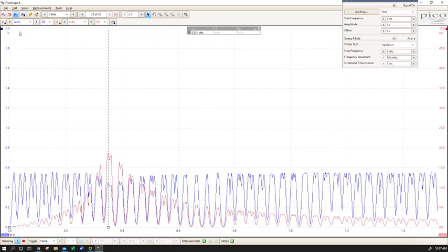And if you look up here at your scales, you can see that it's changing scale for both of our channels, our full circuit voltage and our resistor voltage. And we're getting something that looks clearer and clearer, like a peak and a trough. The peak is clearer than the trough, so we'll use that.